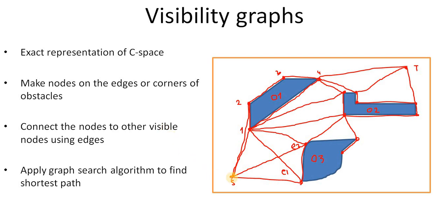And remember that we are taking our robot as a point here. We're taking our robot as a small point, but if you want to represent the robot's exact size, then you have to make the obstacles bigger, which is called inflation of obstacles. If you remember, we discussed this in previous lectures.